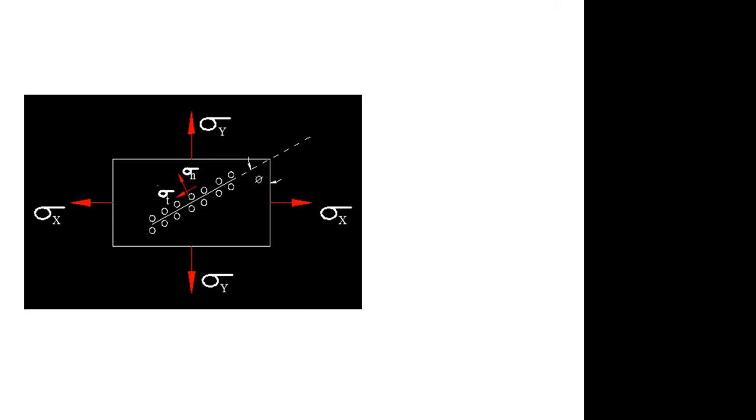Right. So that is the reason for finding sigma n and sigma t. Due to the combination of various loading, it develops different values of sigma n and sigma t in different planes, that is in different inclinations. As a result, if in any one of the planes it exceeds the sigma n limit or sigma t limit of the material, the material will fail. For assessing this, we have different failure theories. This is not the scope of study here, so we can limit it with this discussion and proceed forward.